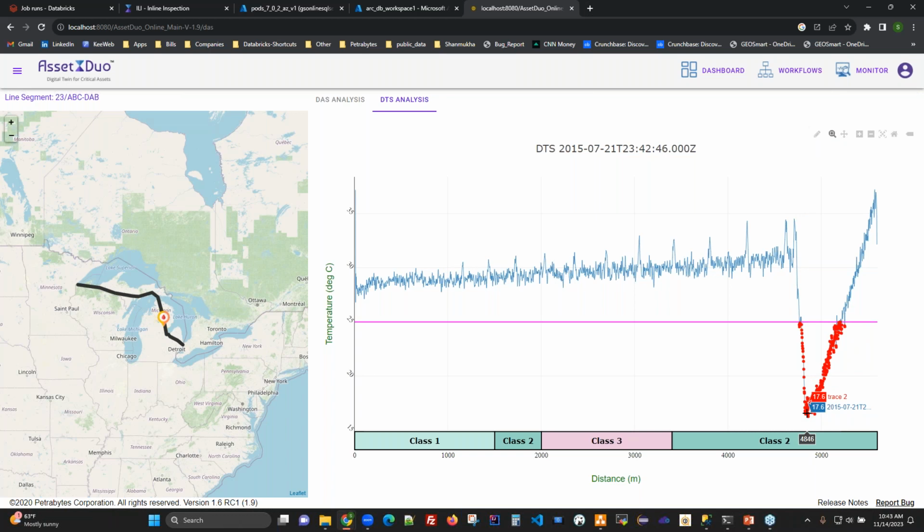Okay? So this is an approach where we are thinking you combine your statistical, Monte Carlo simulation-based ILI analysis risk models with real-time monitoring of your strategic asset, your pipeline, and that is how you are basically mitigating your risk of failure, with quick response to leak detection and so on.